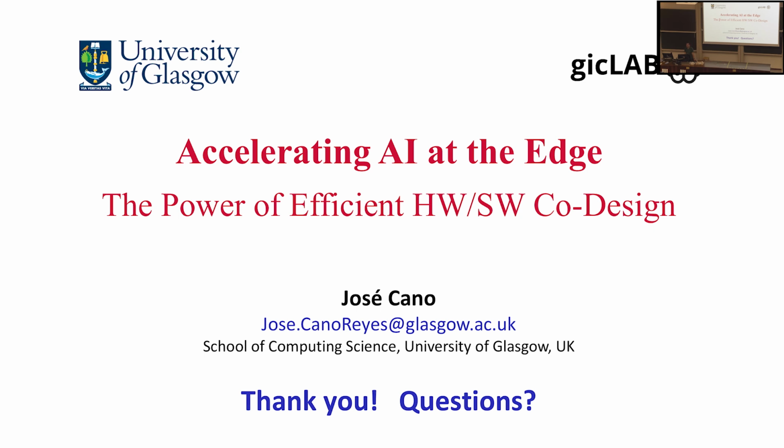Thanks for the talk. I have a question about your matrix multiply accelerator. Did you design a matrix with certain sizes depending on the specific architecture, or can your accelerator compute matrices with different sizes for the same architecture? Yeah, it can. Based on the fabric of the FPGA, you can accommodate a given size of accelerator, right? As I showed you before, we have played with different sizes, but if the matrix that you have is larger, basically you need to do something. You need to do tiling or apply some optimizations in order to split that computation and keep sending chunks of it if it doesn't fit, obviously.